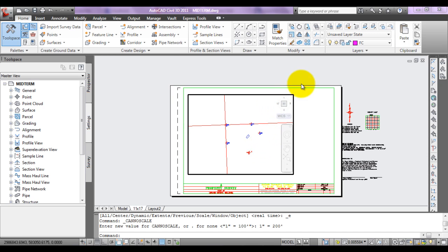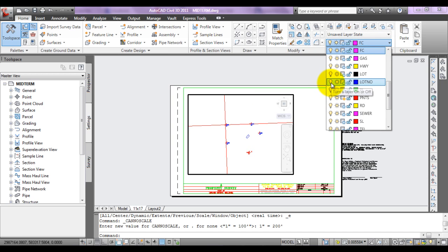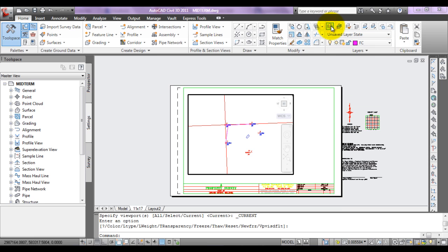So in this drawing, our layers for the new viewport are not showing. If you see here, this says it's on, this says it's thawed, and then this is about the viewport itself. It has a square around it. So if I turn it on, it'll thaw out that layer, right? So there's my fence.